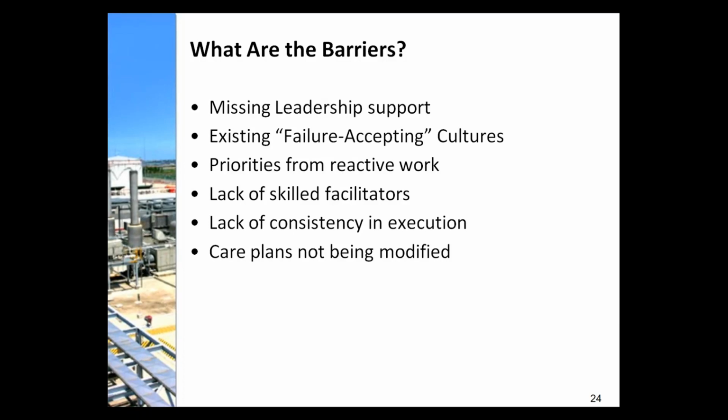Care plans not being modified. In other words, once you have a result from a root cause analysis that says, hey, we need to add a PM for this pump, and the PM never gets put in the system, well, the root cause analysis was useless. And you're just doomed to have that same failure in that pump again.